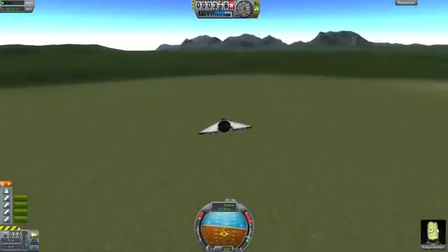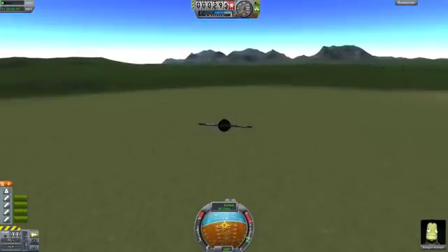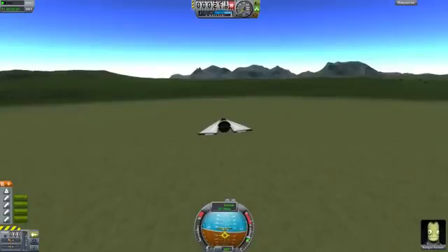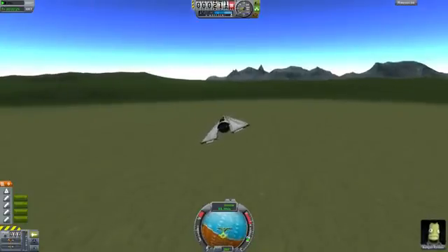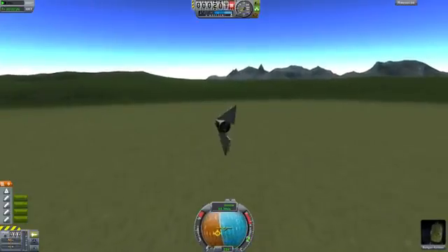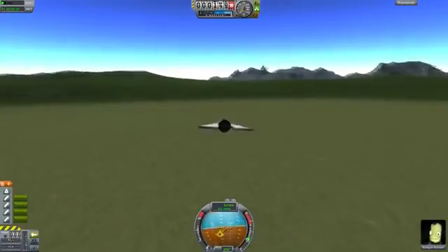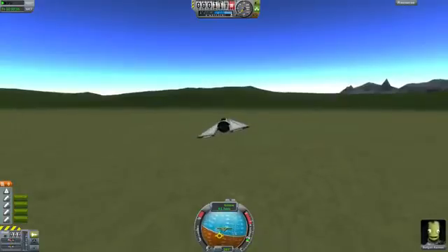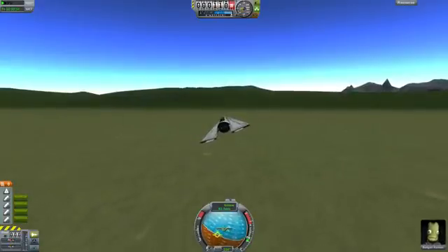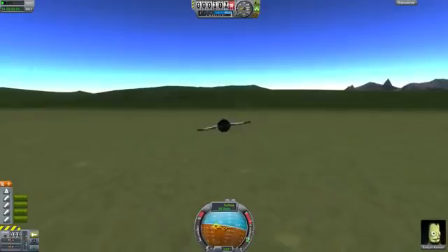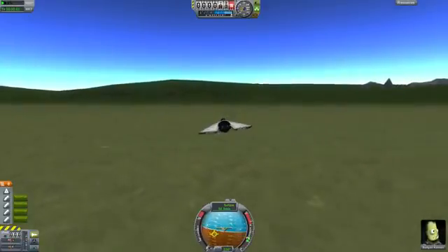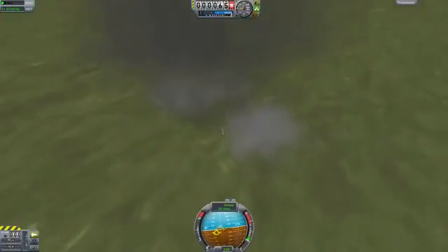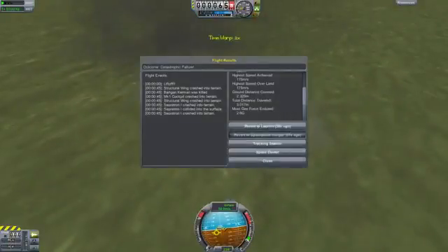It wants to go a little low. I have to really kind of fight it because it wants to go down, but it does actually want to fly relatively nicely. Now, the only problem with this is if I want to turn, right, then as you see, as I start to turn, my velocity vector tends to drop down. What's happening is I'm drifting sideways, and without any torque in the capsule, there's really no way for me to correct this. And, well, okay, I crash in the end again. But that's fine, because this is all about testing.